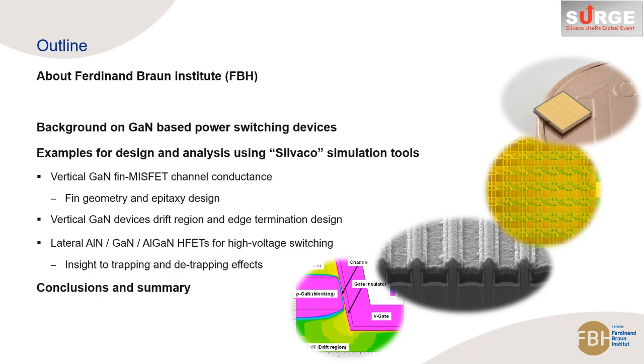There, we'll look at vertical FinFETs, channel conductance, and their geometrical and epitaxial design. We will look at vertical GaN devices drift region and edge termination design. And then we will look at lateral HFET devices with aluminum nitride buffer layer for high voltage switching. There, we will give insight into trapping and de-trapping effects.